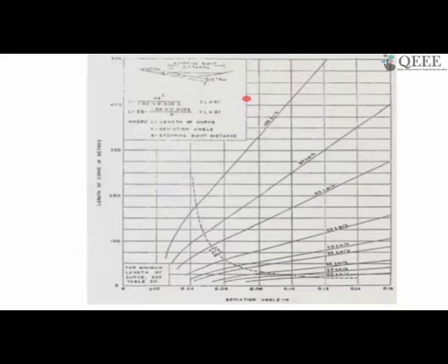And the softwares are nowadays smart enough to tell you where it is not meeting the design criteria, and it will show you in red, and as a design engineer you just need to go and see why it is not meeting, and accordingly you need to change by trial and error method, changing the PI location or fitting with a different curve, or if you need a design exemption from the speed point of view, all those things you need to do. So that is how it is being done.